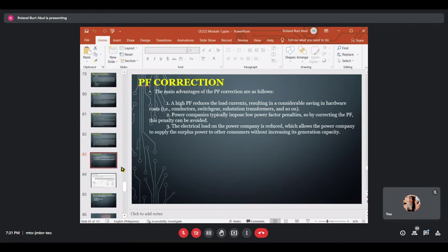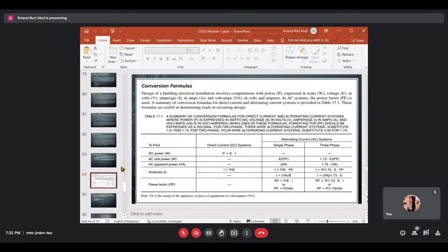A capacitor has the effect of causing the phase of the current to lead the voltage, and thus reducing the lagging effect caused by inductive loads. Capacitors or synchronous motors are frequently used to counter the effect of inductive motors and transformers in industrial applications. Some consumers install power factor correction devices such as capacitors to cut down on higher costs associated with low power factor. For example, modern fluorescent fixtures have a PF correction device that improves PF to 0.90.